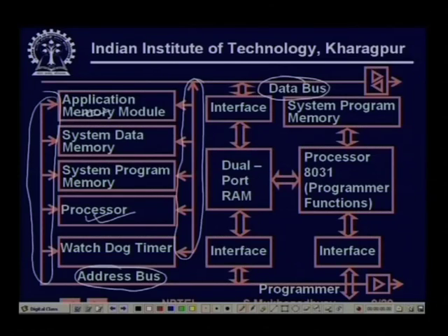You have application memory where the computational tasks run. Even for running tasks, for managing the resources of the PLC you need some programs which are typically called systems programs. So for that you need systems program memory, you need systems data memory.